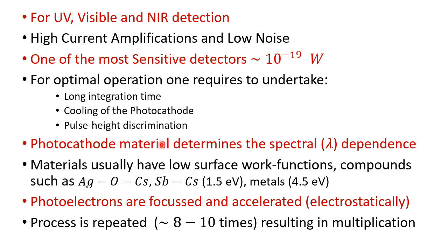All right. And clearly, you know that the photocathode material has a spectral dependence. That is, you require a minimum amount of energy for the photoelectrons to be released from the surface. If the photons do not have that minimum h nu, or the maximum lambda, you will not be releasing the photoelectrons from the photocathode material.